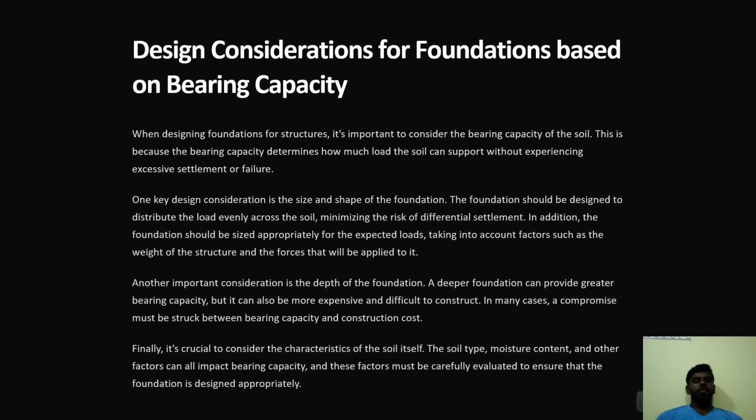In addition, the foundation should be sized appropriately for the expected loads, taking into account factors such as the weight of the structure and the forces that will be applied on it. Another important consideration is the depth of the foundation. A deeper foundation can provide greater bearing capacity, but it can also be more expensive and difficult to construct. In many cases, engineers must strike a balance between bearing capacity and construction cost.